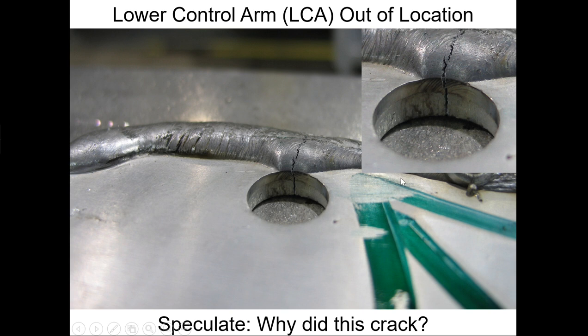It cracked simply because it got so hot. We already talked about expansion and contraction being far more vicious than people think. It got hot, it expanded, and then cooled and pulled itself apart. When it gets hot, it expands and deforms, and then when it tries to cool, it shrinks and literally has to pull itself apart.